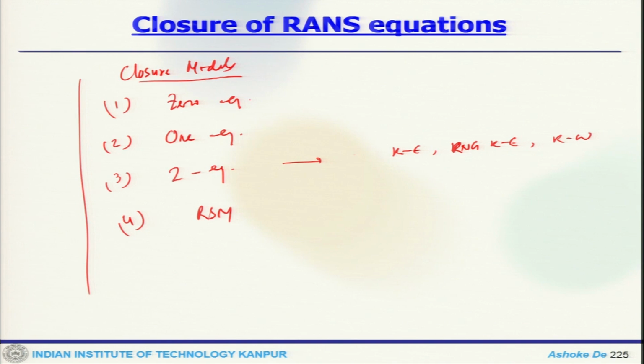So, many turbulence models are based on this Boussinesq hypothesis, and it is observed that turbulence decays unless there is a shear in isothermal incompressible flow.